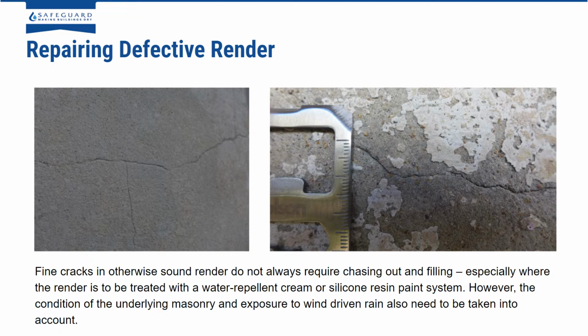But there can also be situations where you turn up at the wall and quite small fine cracks in otherwise sound render do not actually need chasing out or filling, especially where the render is treated with a water repellent cream or a silicone resin paint. But it's always worth checking the condition of the underlying masonry, and if there is any exposure to wind-driven rain, whether this needs to be taken into account.